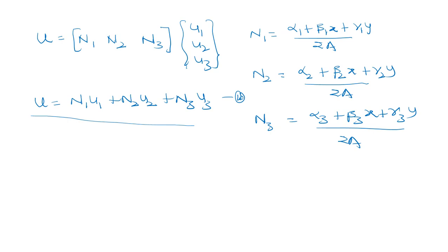Now already we calculated the shape functions for the x components. Then we can write it as v is equal to N1 v1 plus N2 v2 plus N3 v3.